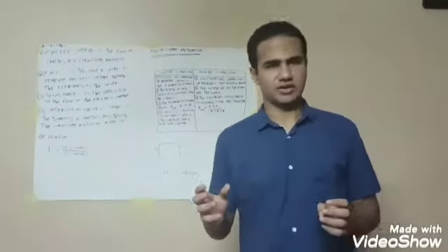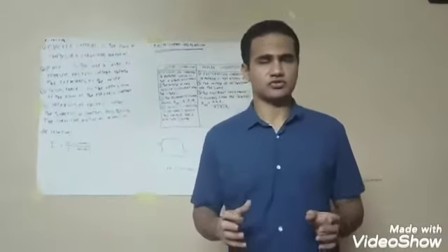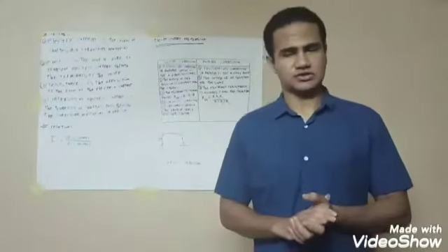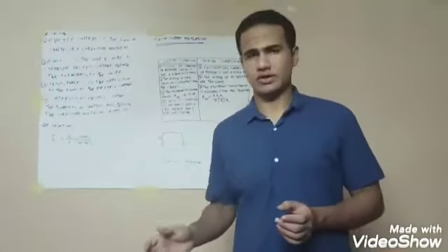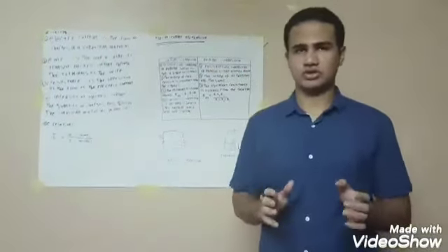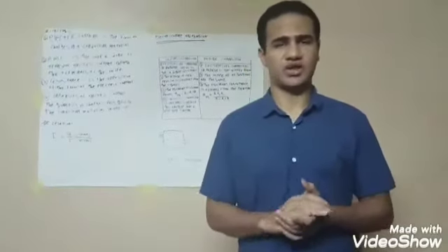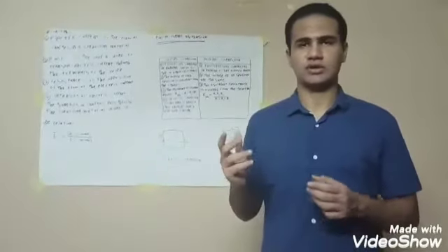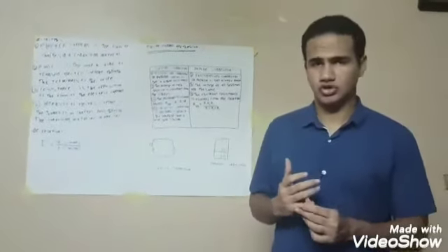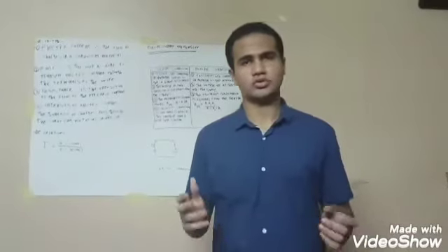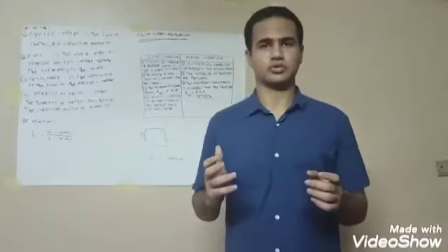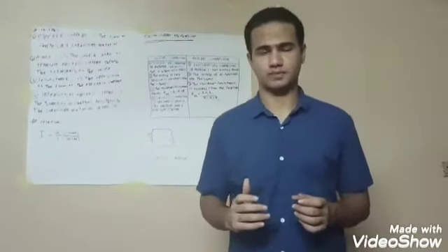And can anybody here define the resistance from what we said? Okay, resistance is the opposition to the flow of the electric current. Now we got to talk about connection in electricity. In electricity we have two ways of connection: series connection and parallel connection. In series connection, resistors are connected together to get a higher resistance, but in parallel connection, resistors are connected together to get a lower resistance.